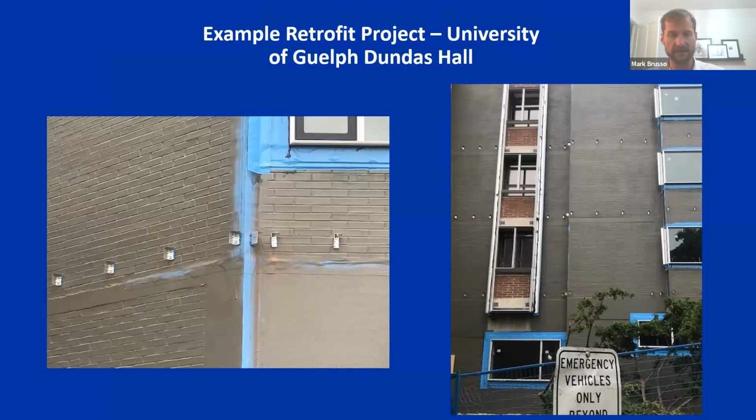And the reason is that a lot of the fasteners and the expansion anchors and the brackets, they perform so well in an intact building, intact masonry structure. So you get extreme fastener performance, very strong pullout values. Essentially, all that brick and mortar was in prime condition because that outside cladding did perform over time. It did its job in keeping the elements out. And what you were left with to fasten to is something very strong.